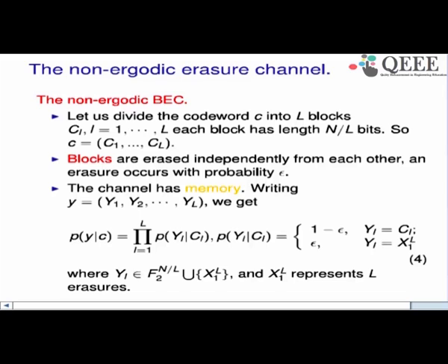Most channels in natural scenarios will be non-ergodic. This is because when you transmit a symbol of a given duration, for example in GSM, the symbol duration would be of the order of milliseconds. But a typical channel in an indoor environment or a slow environment will vary over a duration of seconds. So an entire packet of 1000 bits can go through while seeing the same channel. So you will see this block model coming into the picture.